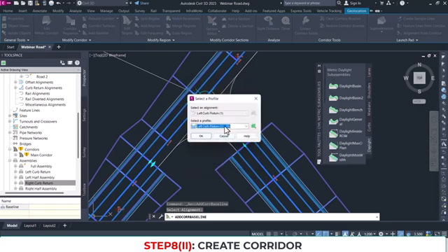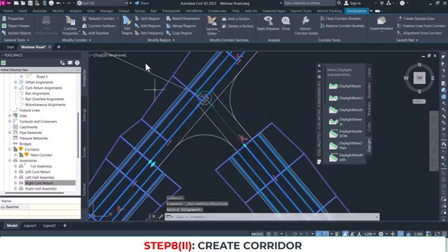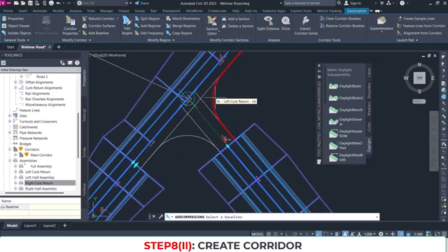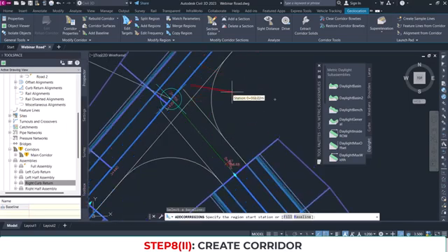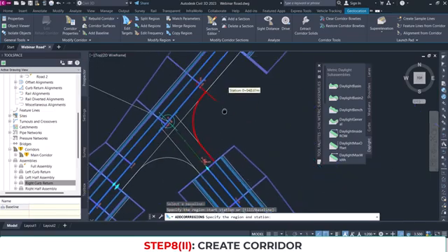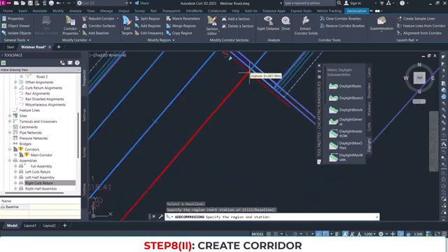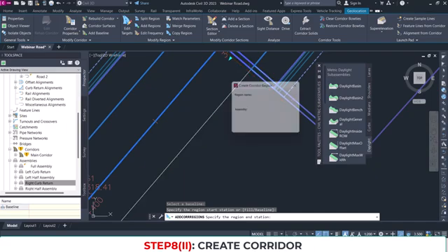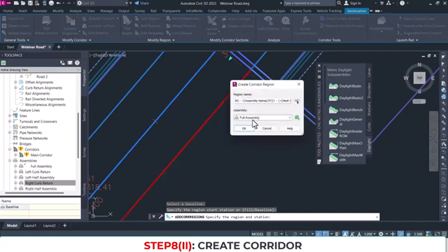I've created a baseline, now select the profile. Now if I want to add a region, you can see it will be highlighted in red. So that's what I'll quickly do now. I'll click on it and then start sweeping from the intersection of this to the intersection of this. Okay, great. So what assembly am I going to use? I'm going to use the right curb return.